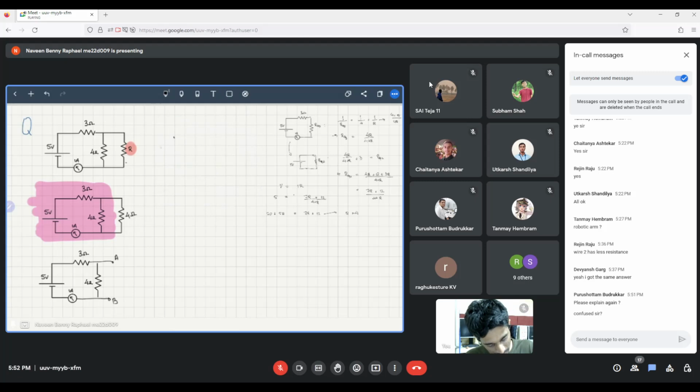So, for example, if you have 10 ohm here and 20 ohm here, then twice the current will go here. If 1 ampere flows in this branch, then 2 amperes will flow here, because that's how it works in parallel, right? In parallel, the voltages are common at the ends. If the voltages are common at the ends, and we have V is equal to IR, that means in this branch, the V is this thing, the current is something, and the resistance is 20.